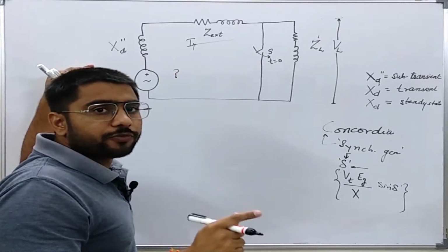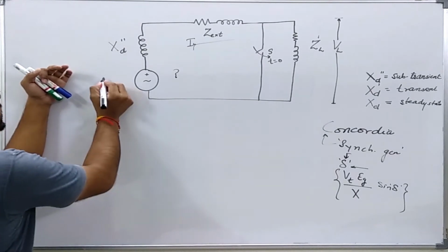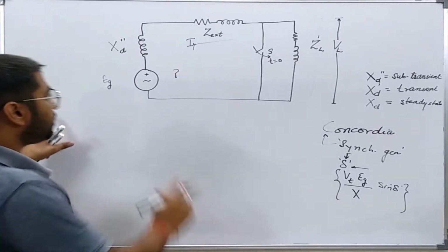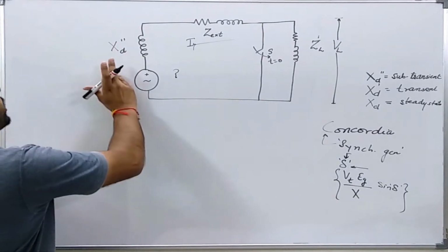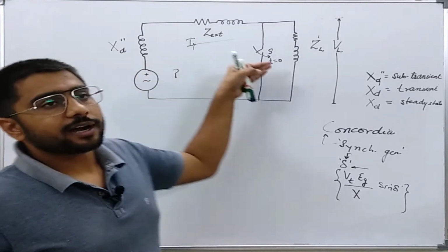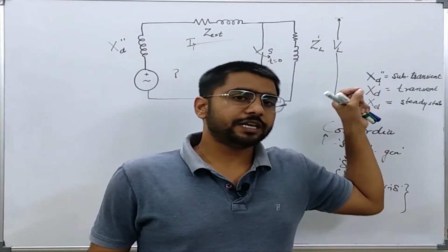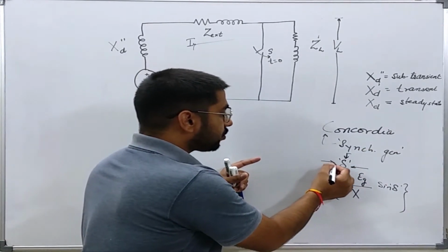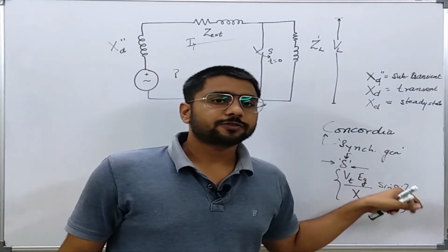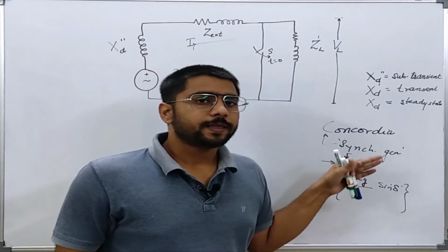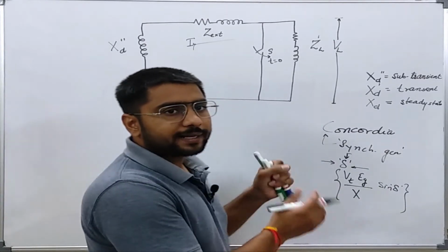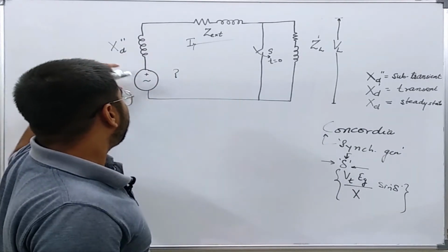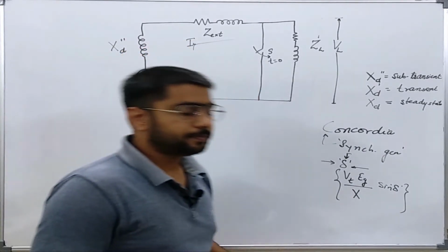Earlier, in the case of the no-load generator, this was simply written as EG, but here we cannot directly write it as EG because this value is going to be dependent upon the load current being supplied by the generator before the initiation of the fault, since there is something called the power angle which controls the power transferred, and this will change also. Because of this, there will be some complex action going on inside the generator, and this voltage will be dependent upon the load current.